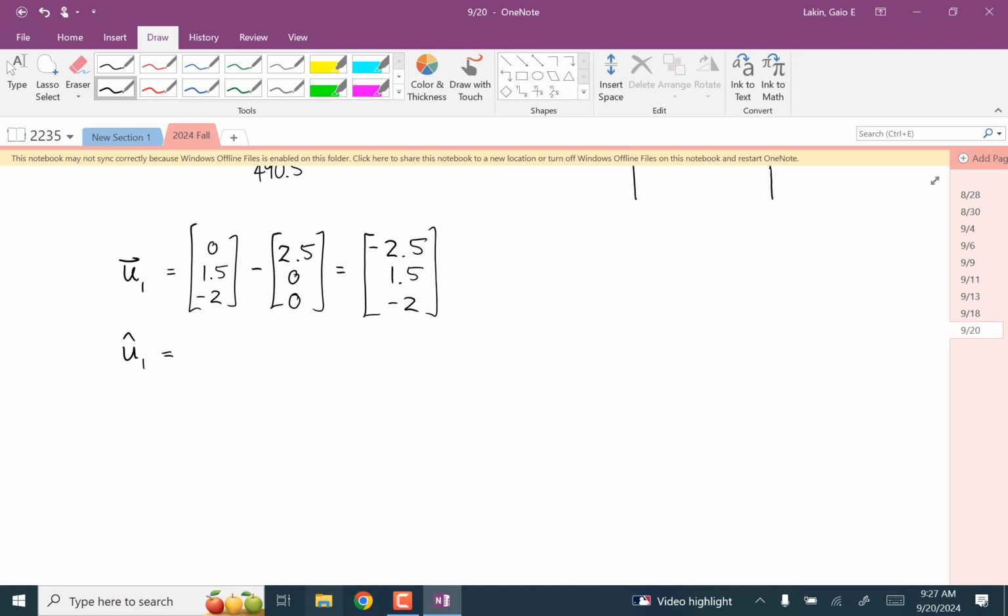But anyways, what you get if you plug it into that program is negative 0.7071, 0.424, and negative 0.566. And you might wonder if it's important that I have 4 significant figures for my X component and 3 for my other 2 components. Yes, it's very important. And so finally, there's our unit vector. And so that force vector is this times T1.